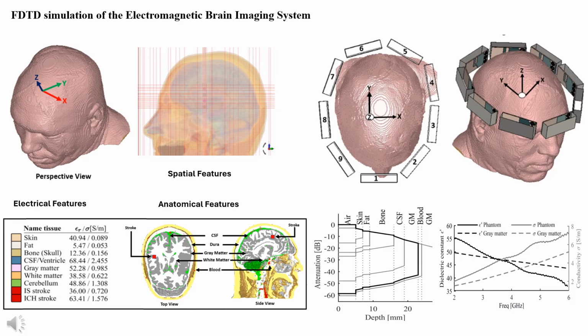As mentioned earlier, the simulation domain is surrounded by PMLs to absorb outgoing waves and prevent reflections that could affect the accuracy of the simulation. The integration of the human head model into this domain allows for a realistic simulation of electromagnetic wave interactions in a controlled environment, where the FDTD method can compute the field's behavior over time.